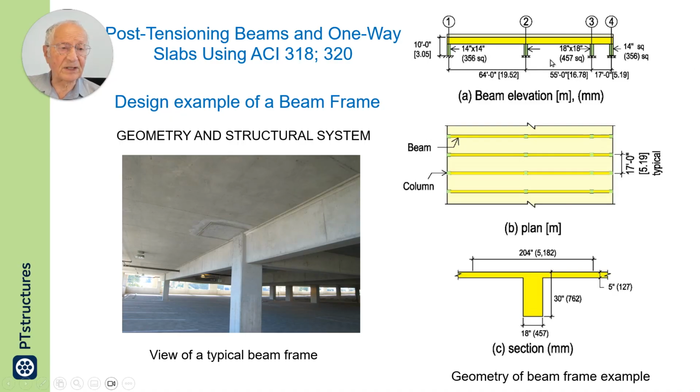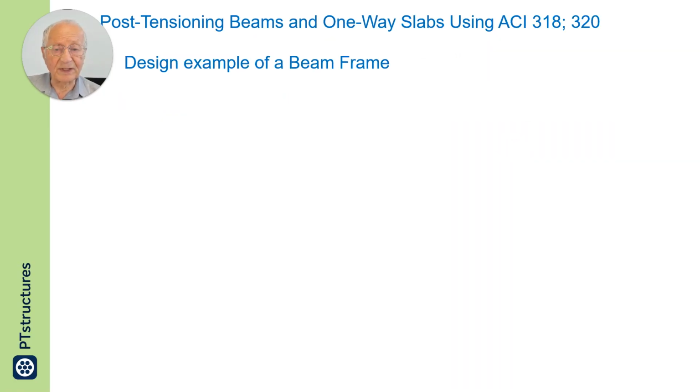This geometry that I have selected will result for optimum design in post-tensioning tendons being of different values in the three spans, which will require design of a condition where tendons are not all the same from one end to the next.